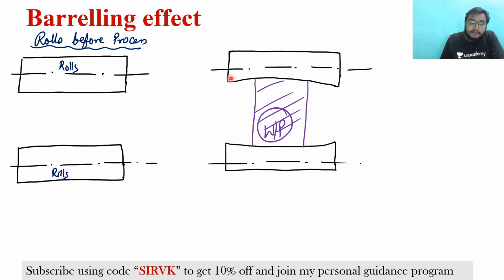Your earlier roller was like this, now the roller is like this. So there is a difference in the cross sections and the area. So what we can understand here is that if I use any workpiece during this rolling operation, deflection causes the workpiece to be formed with the barrel shape. What is the meaning of barrel shape?